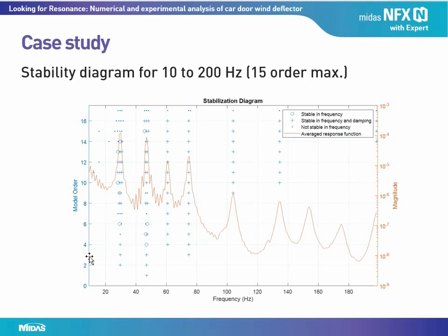For the first single order trial, the algorithm could only find the frequency and damping for the peak near 50 Hz. It is interesting to see that 3 peaks in the upper band are not recognized by the fitting algorithm. To solve the problem, we can resort to more powerful algorithms, or fit a narrower band each time.